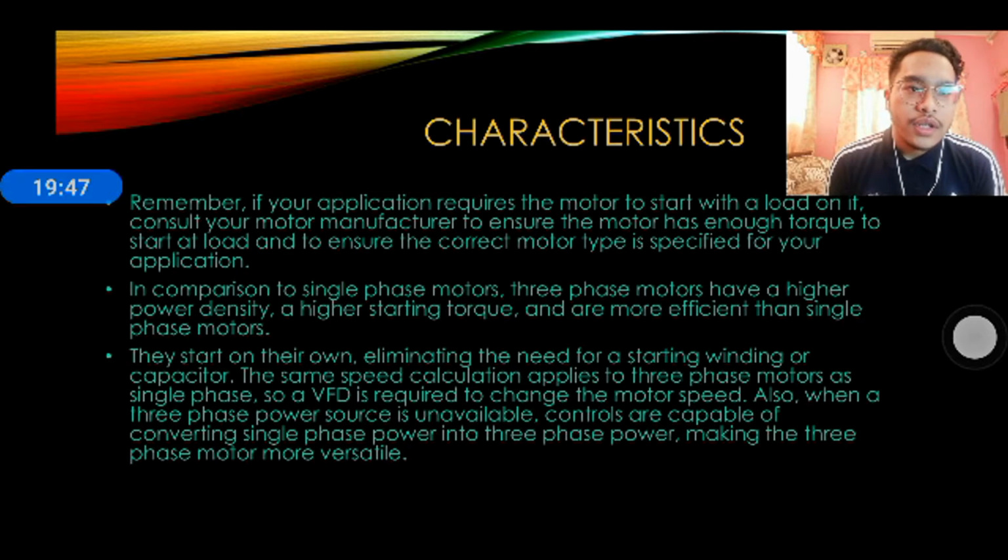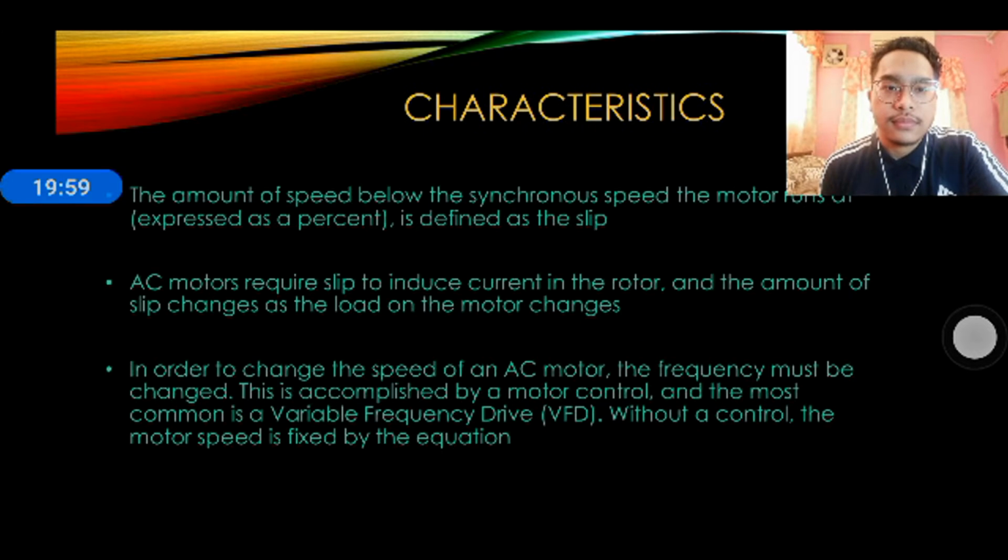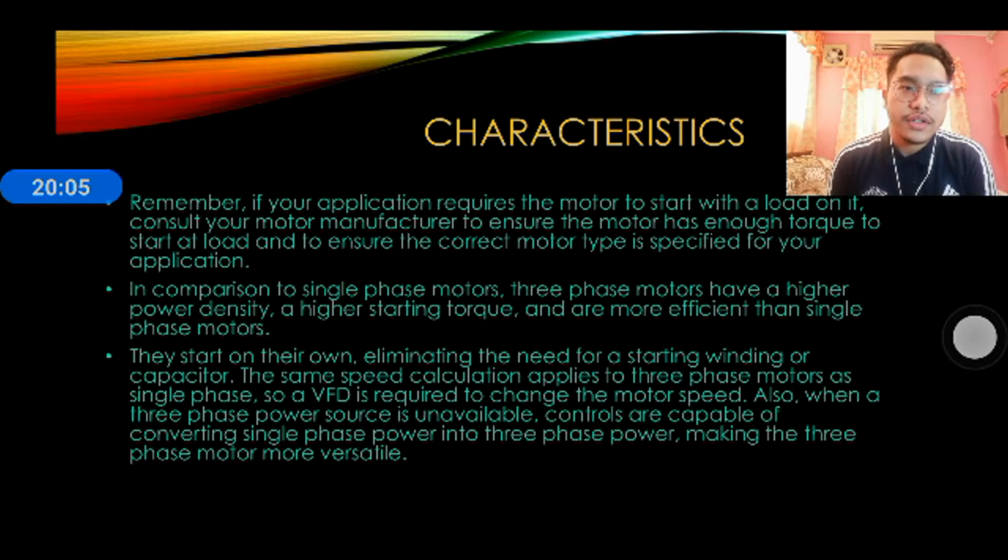The same speed calculation applies to three phase motors as single phase motors. So the VFD, variable frequency drive, is required to change the motor speed. VFD changes the frequency, then it will change the motor speed. Also, when the three-phase power source is unavailable, controls are capable of converting single phase into three-phase power, making the three-phase motor more versatile.